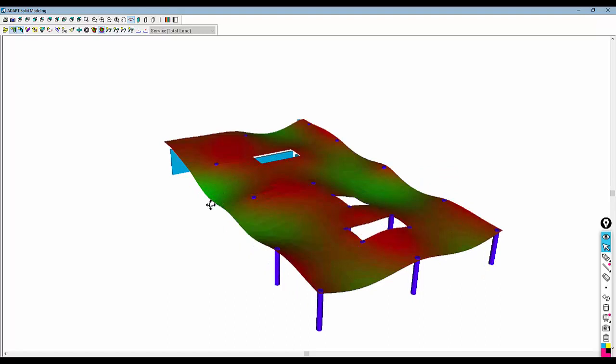So the user would then be able to determine, okay, under linear elastic conditions, if we apply just a multiplier maybe to predict long-term effects on top of that 0.33, does that satisfy the requirements and the limitations for deflection control in different regions of the slab? And there are ways to predict the long-term deflection and the cracking in the slab. Those are reviewed in another video. But the 0.33 is just an immediate deflection under service total load. So this is unfactored load for dead, self, and live load.